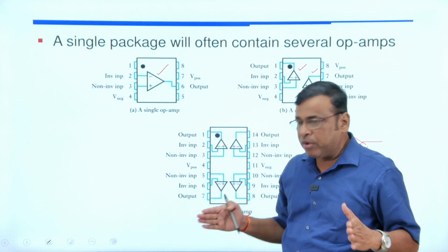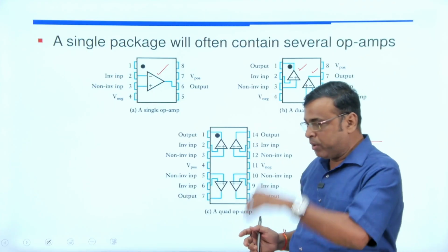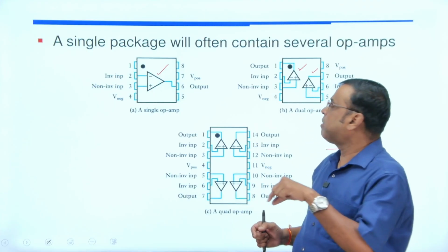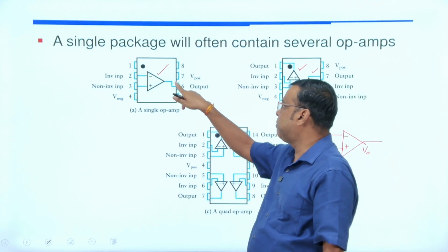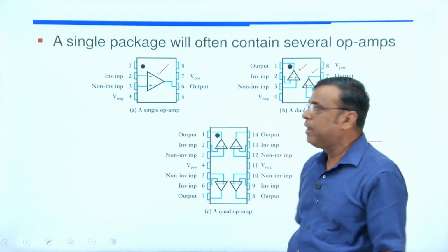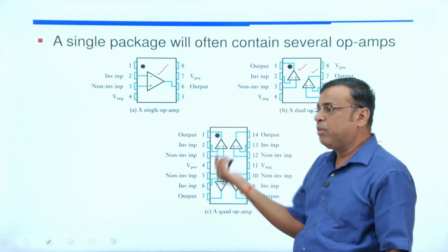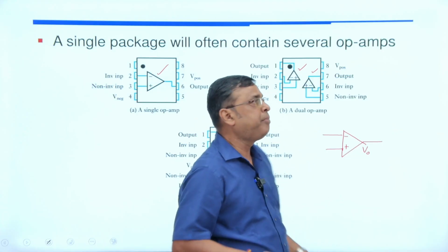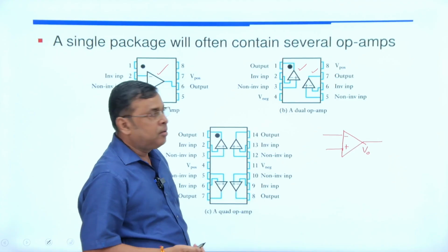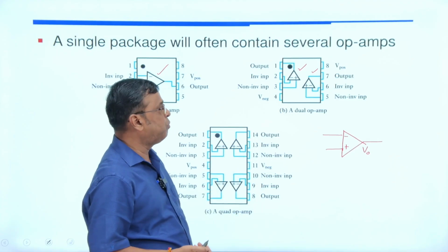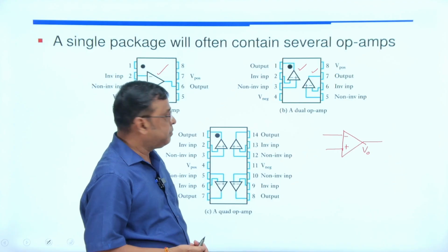On a breadboard or simply a designing board, you put your operational IC in that board, and if you connect the input, the inverting and non-inverting terminals and the output terminal, you will find the output with the help of the CRO, cathode ray oscilloscope. You will see whatever output is obtained in the CRO.